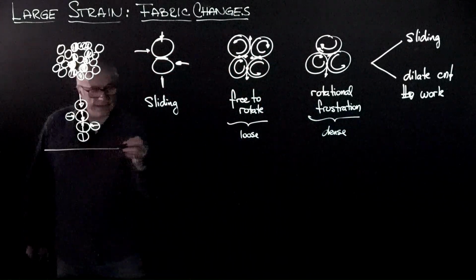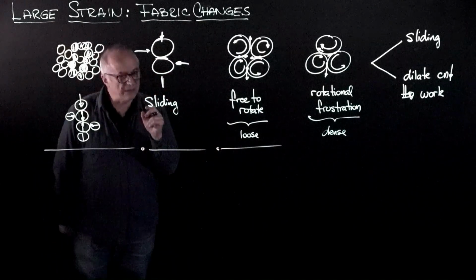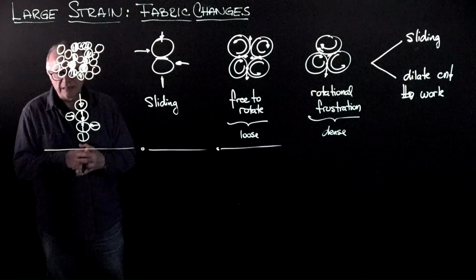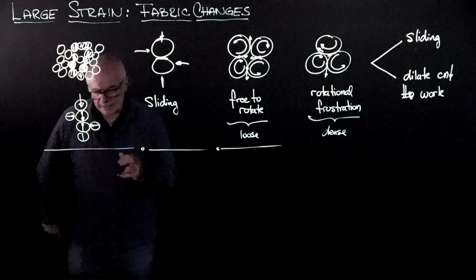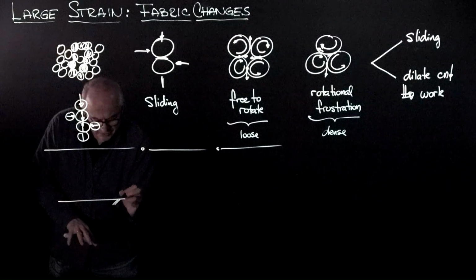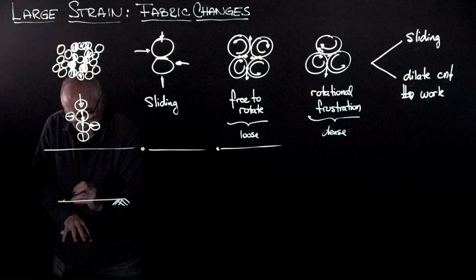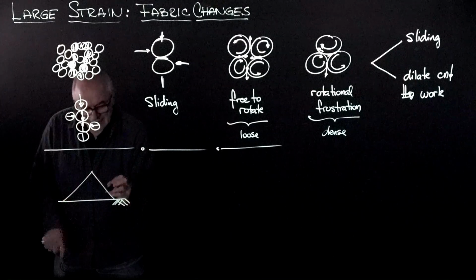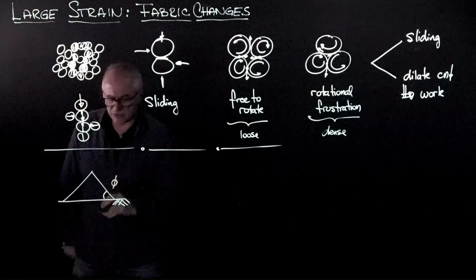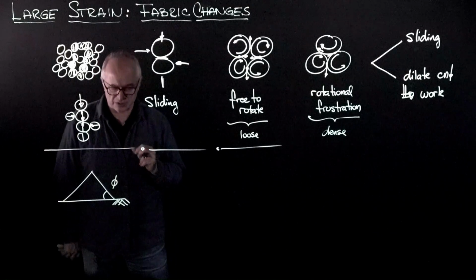The next thing that we can begin explaining when we look at the particle level using discrete elements and particle scale analysis is the following situation. If I pour sand on top of a table from a funnel, eventually I form a cone at the angle of repose. This is the angle of repose that somehow resembles the angle of internal shear strength of the soil.